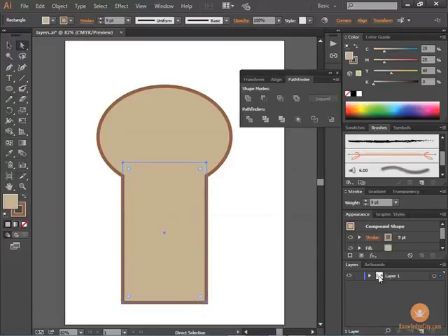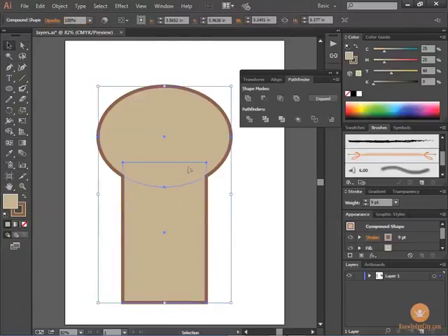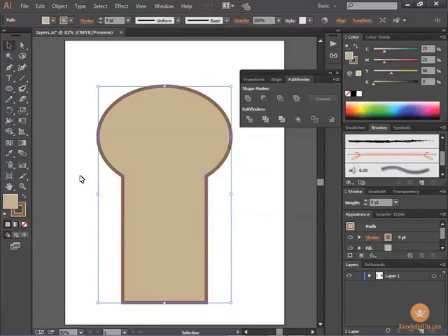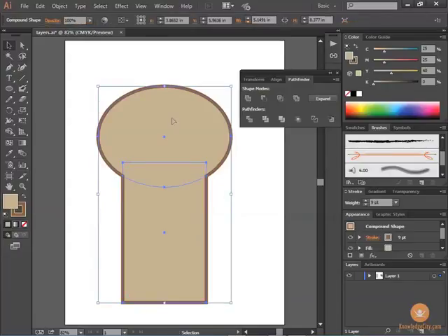So in the end, before you get ready to print, what you're going to want to do is select any of these compound shapes that you have and then click on Expand, because Expand will reduce them into a simple basic shape. But you can keep it editable for as long as you want until the very, very end. And honestly, I would try printing it first and making sure that I have a problem before I come in here and try to expand.